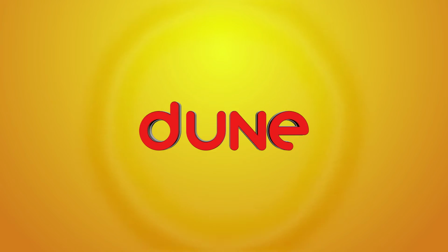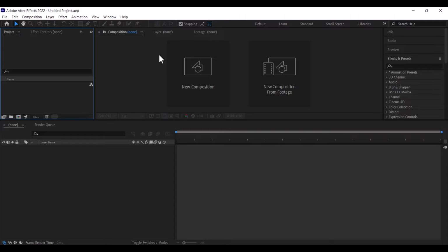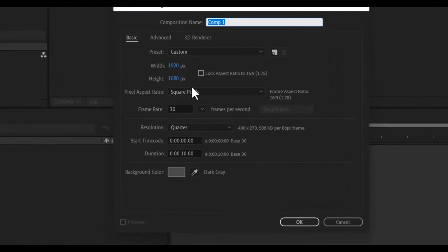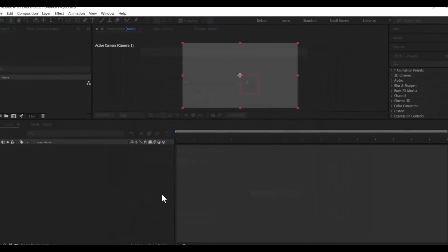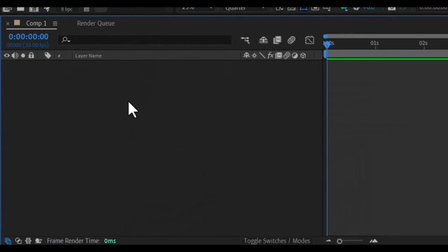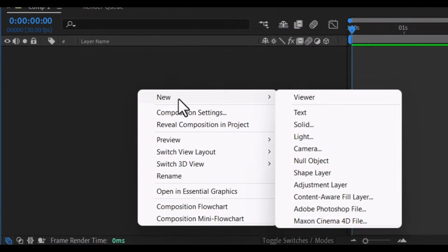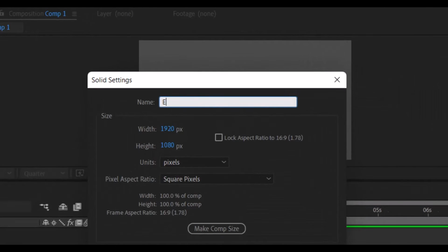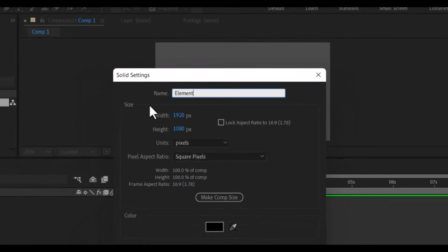Hello, in this video, I'll show you how to create this 3D text animation in After Effects using the Element 3D plugin. So let's begin by creating a new composition. I'm going to have a width by height of 1920 by 1080 with a frame rate of 30 and a duration of 10 seconds. Click OK. Then we create a new solid by right-clicking in this area, go to New, Solid, and I'm going to rename this Element. Maintain the size and click OK.